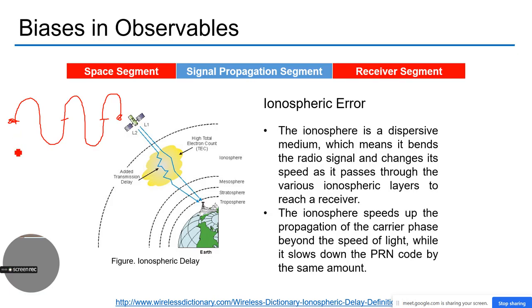So how many full cycles do we have? This is the first full cycle, then this one is the second full cycle. And then we have another cycle which is just a half cycle. It's not a full one, it's just 50% of a cycle. We define phase as 0, 90, 180, 270 and 360 degrees. So here our phase becomes 180 degrees. And in terms of a fraction, it is lambda by 2.